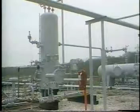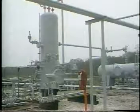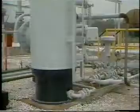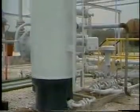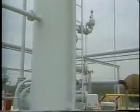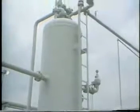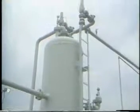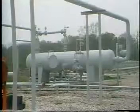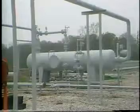It should be pointed out that vertical vessels also have some drawbacks, which are not process-related, but which must be considered in making a selection. For example, the relief valve and some of the controls may be difficult to service without special ladders and access platforms. In general, horizontal vessels are the most economical for normal oil-gas separation, particularly where there may be problems with emulsions, foam, or high gas-oil ratios.